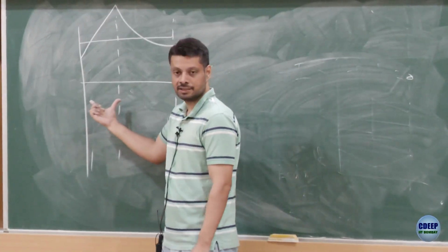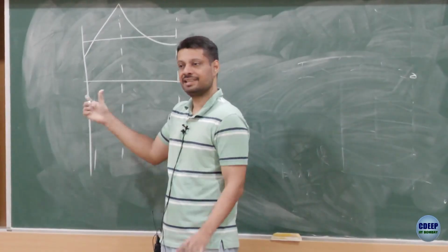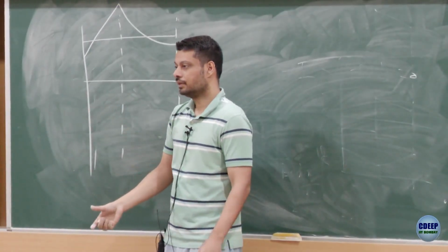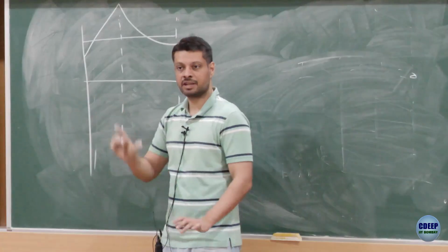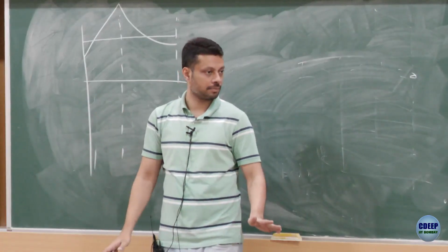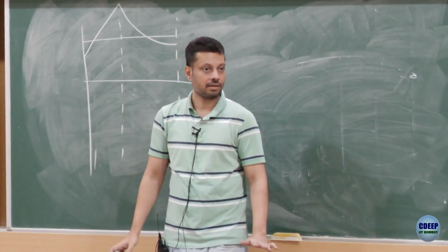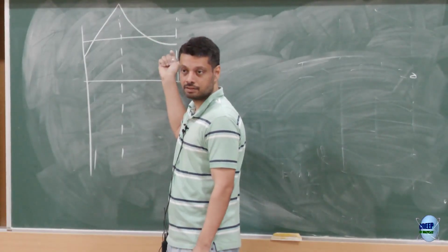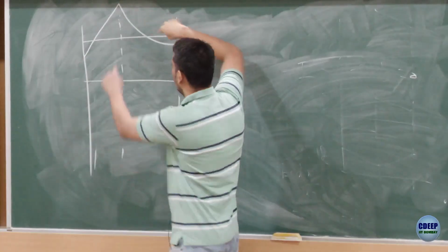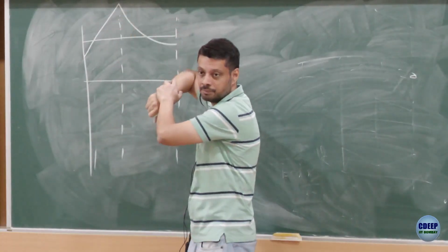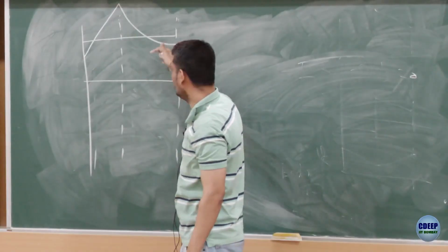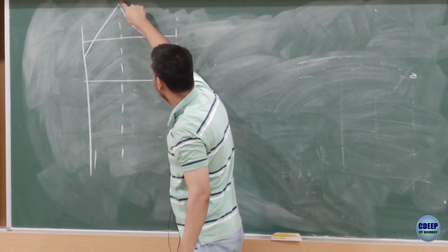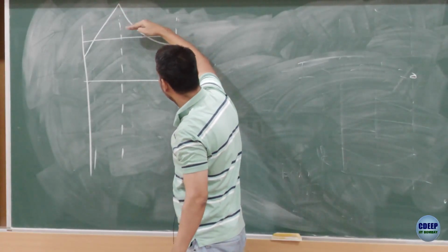In the on duration, the average voltage applied is still the same. So that means in the off duration, the average voltage applied should still remain the same, because the circuit is in steady state, right? This falling thing is exponential, right? So now if these 2 points are far apart instead of being the same, and you want to keep the same average, then in this waveform, if this is the starting point and this is the ending point, the average will not be at the midpoint.